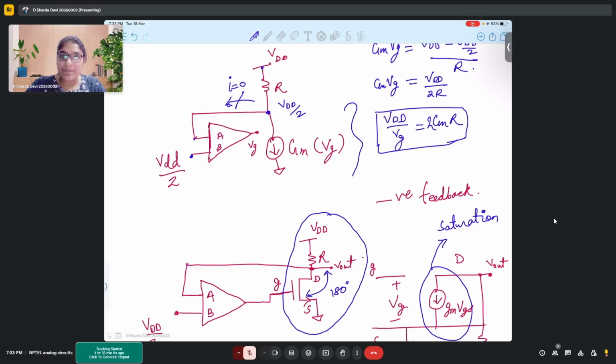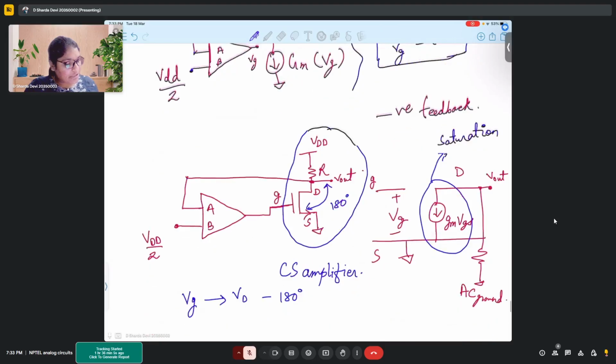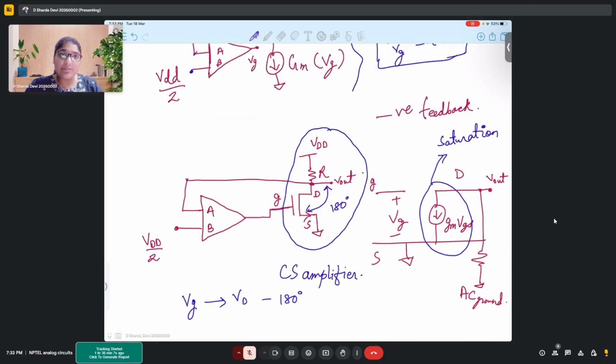No, madam, it is not open circuit. You said it is a small signal model of MOSFET, right? Yeah, in case of small signal model, how does the output look like? Then the current is going to the gate terminal. After the gate terminal, where? I'm saying no, the gate does not carry any current. In MOSFET, there is no gate current.